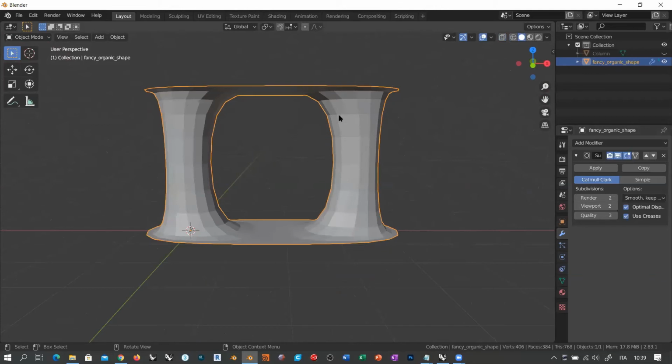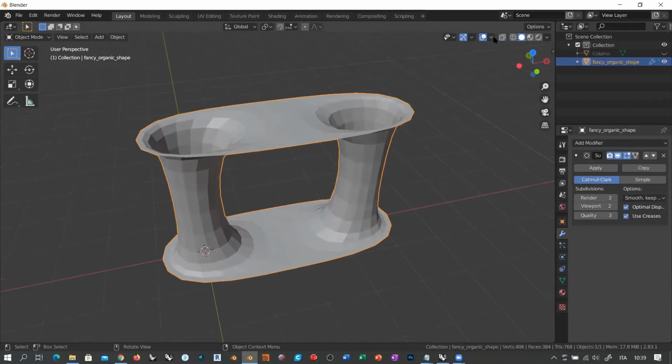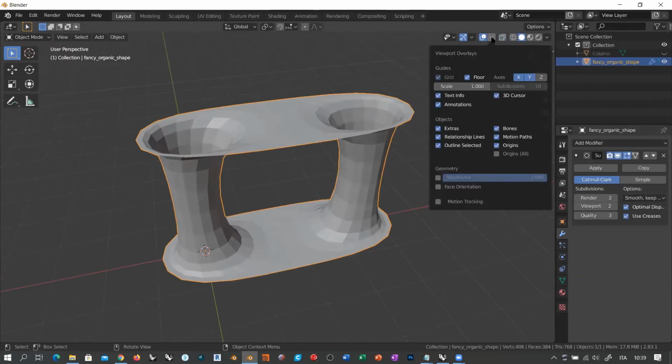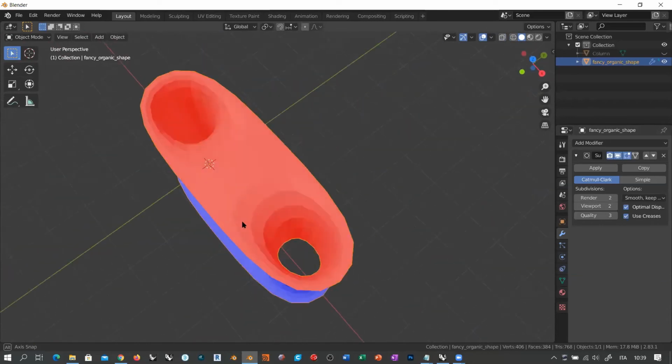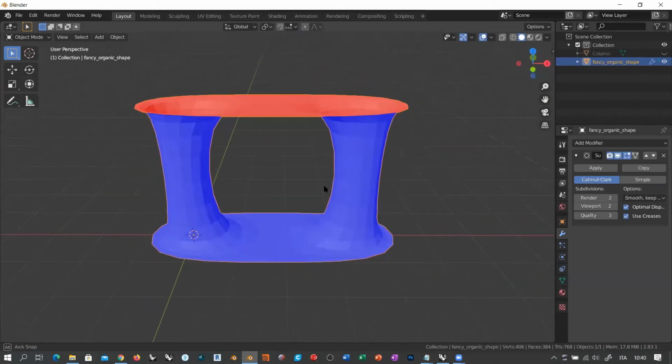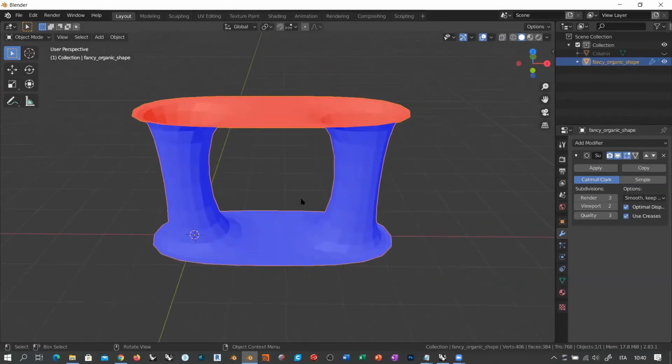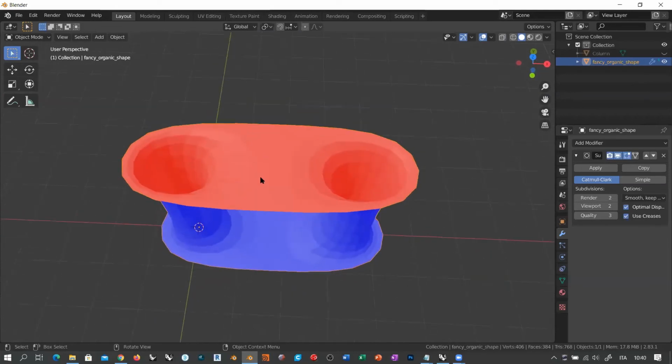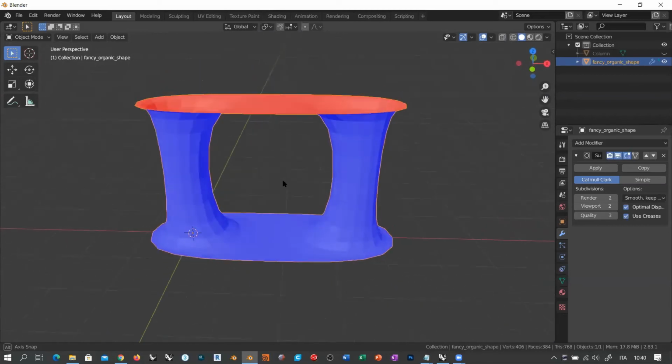Okay, and it's also important to understand what the positive and negative orientations are. So from now on and then, you might want to activate the face orientation. Okay. So you see the positive is blue and negative is red. So everything is looking perfect. We don't have any flipped normal along this mesh. When you see, let's say, a wide surface with this red color, and suddenly you see some blue square or blue area, small areas, in that case it means that you have some orientation problem for your mesh.